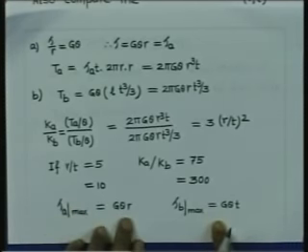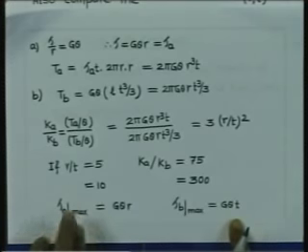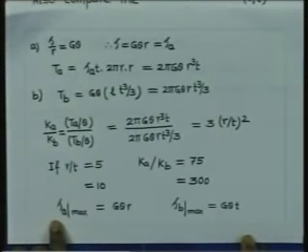If r is larger than t, you are going to get larger stresses developed in the closed section compared to that in the open section. Also, you have seen that the stiffness in the closed section is much higher. So, the torque capability in the case of the closed section is much higher, and also the stresses developed are much higher.